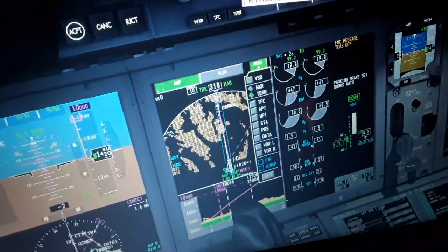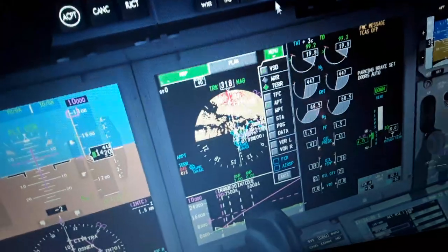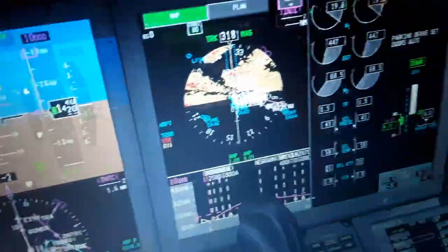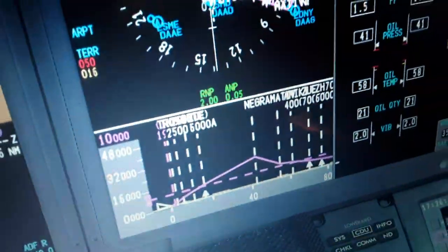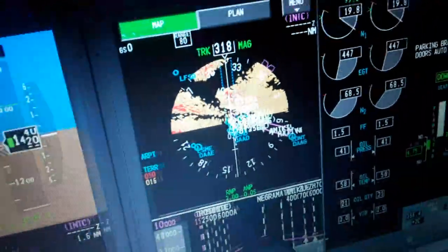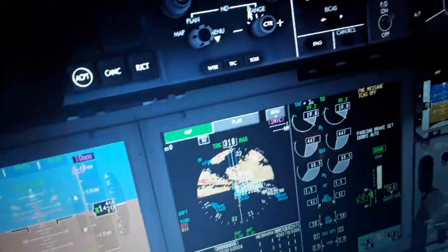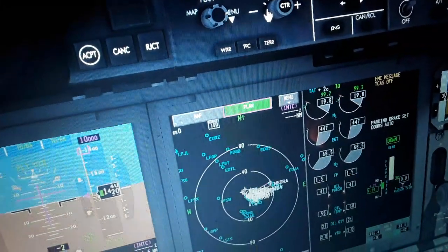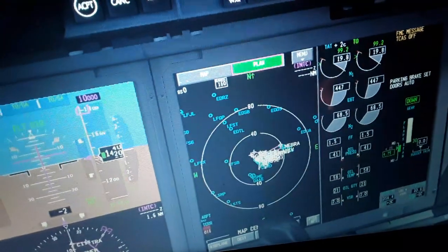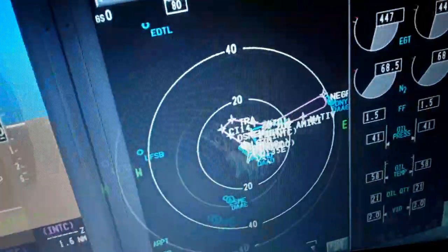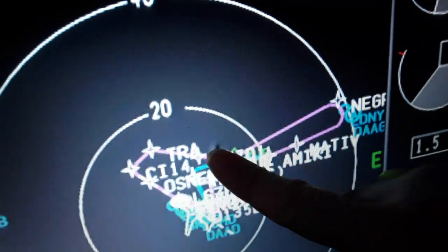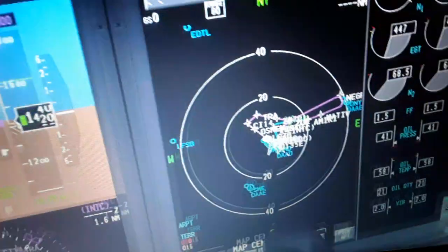We have also the center display. You can see the 360 degrees. The flight plan we have created, the waypoints we have to cross through here as we're gonna be flying. As you can see here in flight. So we can change also other modes here. You can see more airports, the waypoints again, the flight plan we have created from takeoff from this runway, climb, cruise, descent, approach and landing one by one.